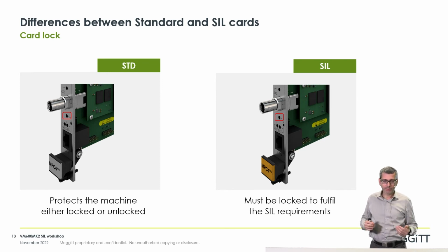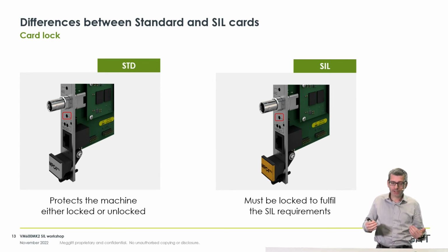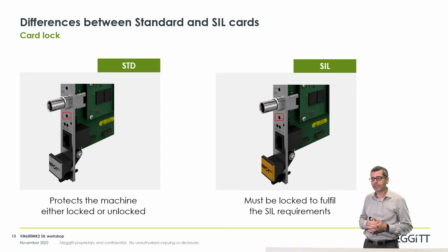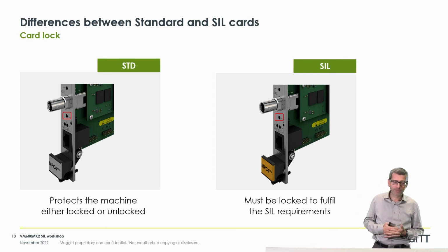The card will protect the machine once it's configured and the configuration is signed. But when the card is locked, there are additional validations, additional diagnostics that are run, and without those additional diagnostics, the card itself doesn't meet the SIL requirements. So it is mandatory, and it will be stated that way in the SIL manual. It is mandatory to lock the card, for it to be sealed.